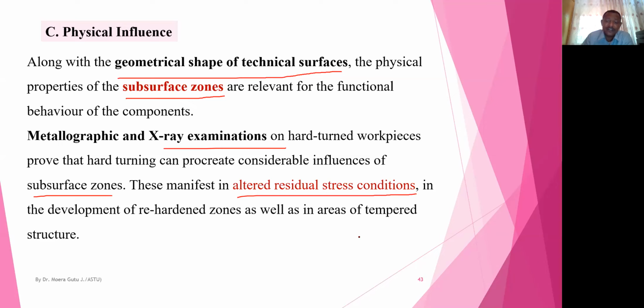The machined surface can have different strengths, hardness, wear resistance, and corrosion resistance due to the presence of residual stress in the surface or subsurface. So this can be reduced by either right implementation of optimized cutting parameters used in machining hard materials, or a heat treatment process after machining.